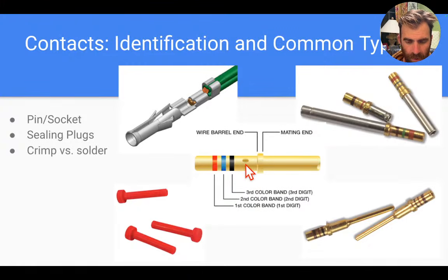That's just used to show that the length of wiring that you have stripped is long enough to fit into the pin or the contact rather. So when you crimp the area behind it, you make sure that you have enough wire in the barrel of the contact, so that you're getting a good connection.